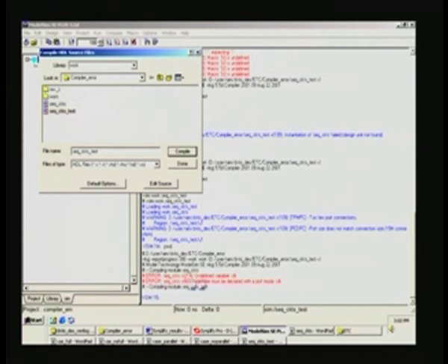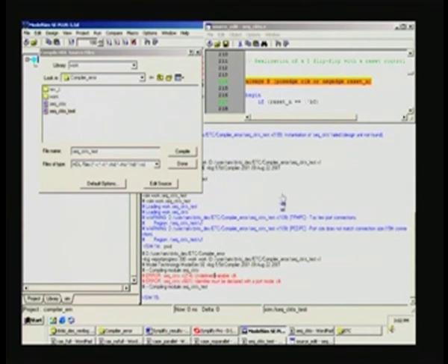We changed the name to clock, so it promptly says that undefined variable clock is encountered here. And this is just a warning saying that I have changed the source file. You can just ignore that. It opened the source file and is pointing precisely to the place where CLK is used, because this is an undefined variable.